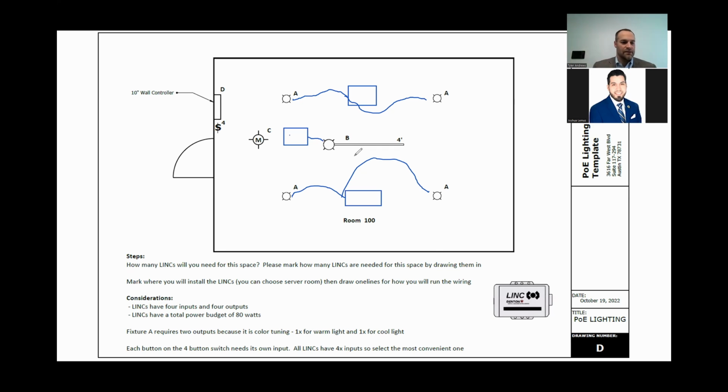I was going to use constant voltage, but it doesn't. So Gary's asking, could he do this in constant voltage? And that's a good question. If these are constant voltage fixtures, yes. So if I would have 1 zone for A. Yep. Or 2 zones, 1 for the color and 1 for the other, and then I've got the track line here. Yeah, so Gary is saying I would do 2 zones with a constant current or a constant voltage light fixture. So if you were working with a constant voltage light fixture, you could operate it that way.